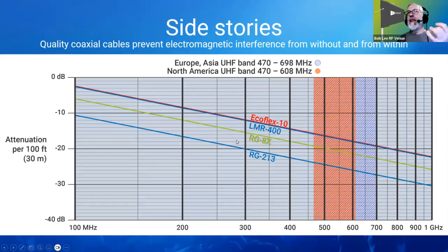So the cool thing about RF over optical fiber is that you can go as long as 5 kilometers, and it is also flat. You don't get this high frequency roll off. It's flat across the spectrum. And so that's to your benefit.